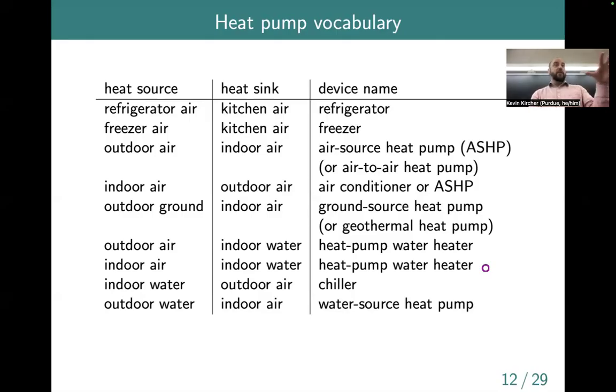So there would be a cold coil that's outside of, say, the tank of water, and we might have moisture condensing on that coil. That can be valuable if you have a humid basement and you don't want mold and stuff like that to grow; bringing some moisture out of the air could be beneficial. Conversely, if you're using a heat pump water heater in this configuration in winter, you're actually air conditioning the air a little bit, and then you have to heat it back up using some other piece of equipment. So you have kind of dueling equipment, if that makes sense. Yeah, but good question.